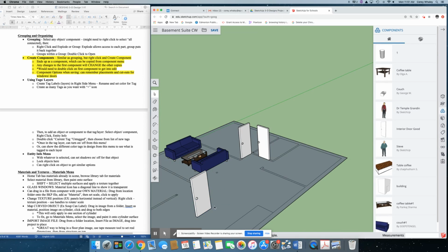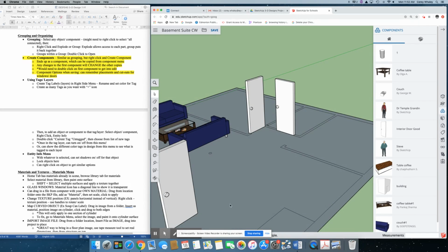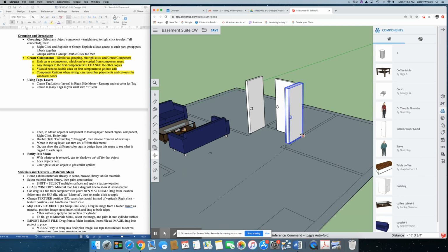And I'm going to move that door into place. And I'm just going to show you how I snapped it. Actually, I can move it to that one too, either or. Might as well do that. So we'll zoom in, and I'll show you how that move tool works really, really well. So if I select that, get my move tool, I can select this bottom corner, and then I can actually snap it right. So I just click that bottom corner, and then I'm moving my mouse, I'm not dragging. So I move my mouse to that other point right there and just click it, and that sets it in place way, way faster. Okay, I'll finish off the doors.